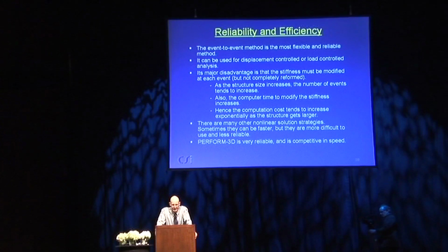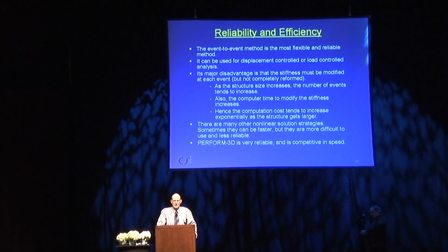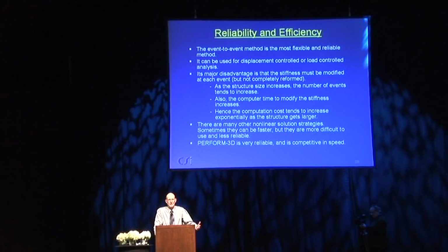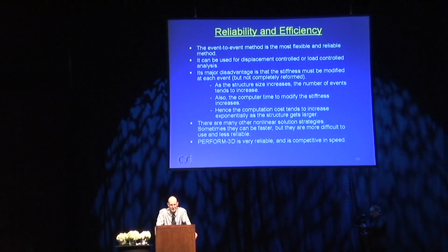The disadvantage, though, is that as the structure size increases, a couple of things happen. The number of events tends to increase. It's just a bigger structure. There are more events that can occur. And at each event, you have to modify the stiffness, so the computer time to modify the stiffness increases for each event. So you have more events, more time to modify the stiffness for each event, and the computation cost tends to increase exponentially as the structure gets larger.